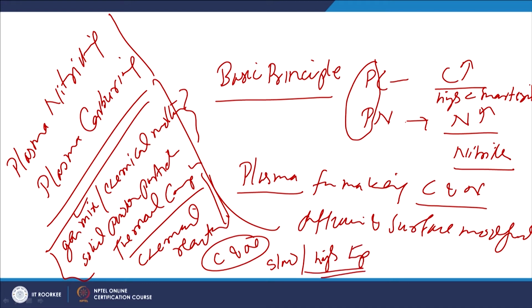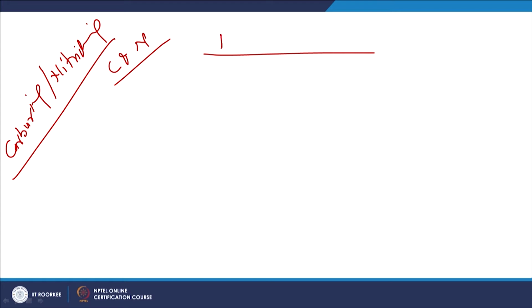High temperature is needed so that we can get a sufficiently high diffusion rate in order to achieve the required depth of the modified surfaces for surface property enhancement. As compared to our conventional carburizing and nitriding process, where a lot of thermal decompositions and chemical reactions take place for making the carbon and nitrogen available at the surface so that these can be introduced at the surface,